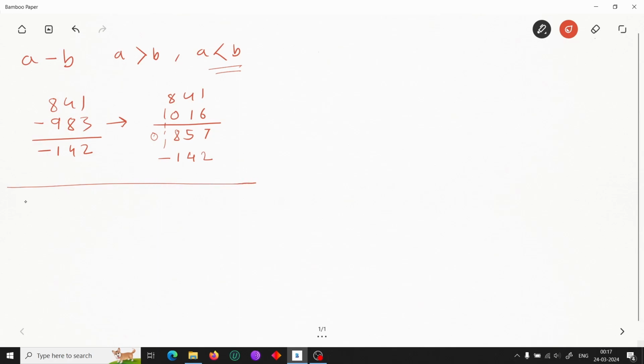Okay, say I want to start from 1100 and I want to subtract 1110 from it. Okay, so like before, 1100, then find the complement of this, that would be 0001, perform the addition, 1011, and then see for ourselves, no carry was generated, so we need to find the complement of this, that would be 0010. So the final answer is minus 10.